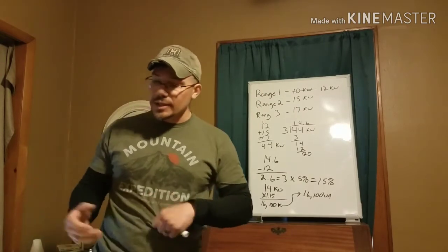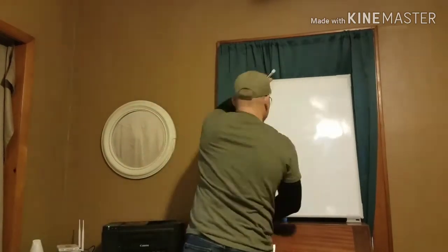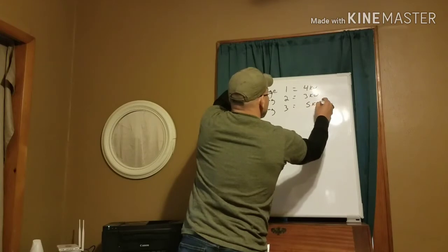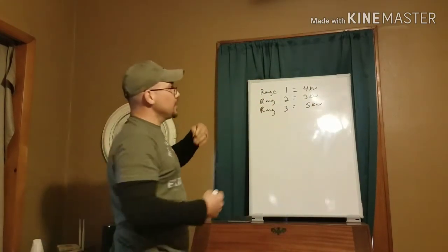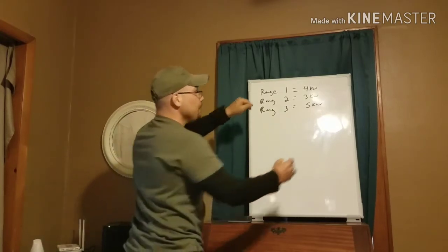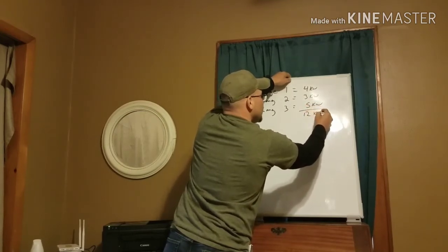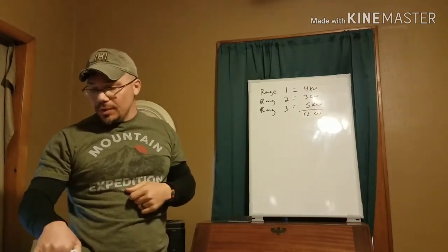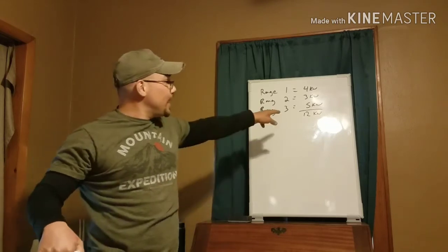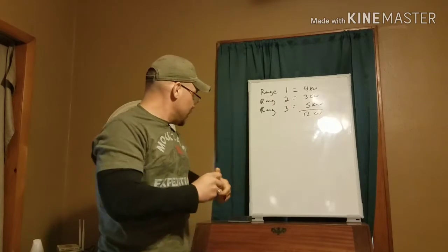Okay, so basically what that's saying is, and I'll do a little bit of math here for you. We have 3 ranges: 4 kilowatt, 3 kilowatt, and 5 kilowatt, right? Since they're below 8 3/4, we're going to add them together, which would be 12 kilowatts, right? Now it says we have to use the column, which in this case is going to be over 3.5, or 2 of them actually.